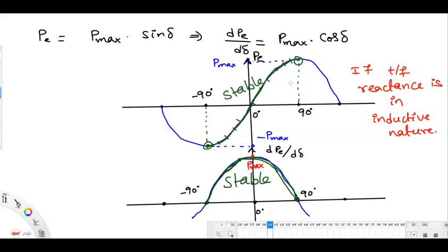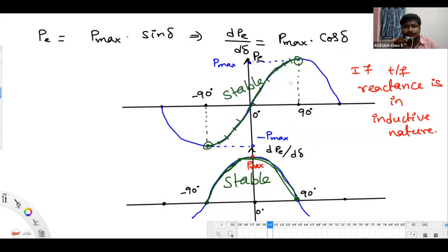Sir, in the midpoint compensator, it will increase the Pmax, but practically it may not be double. So if we want to obtain the maximum power, we should keep it at the midpoint. Midpoint, yes.